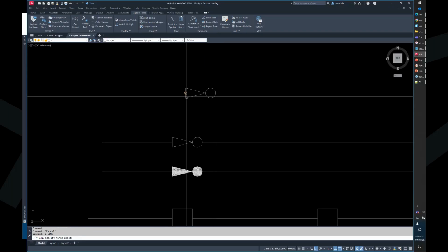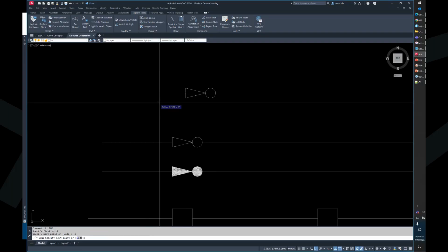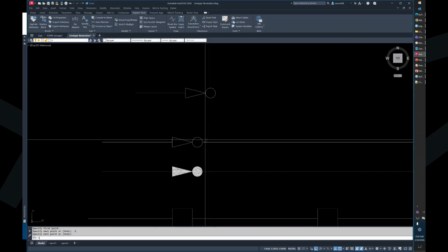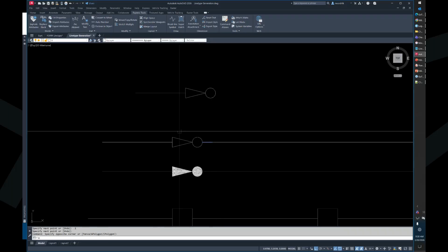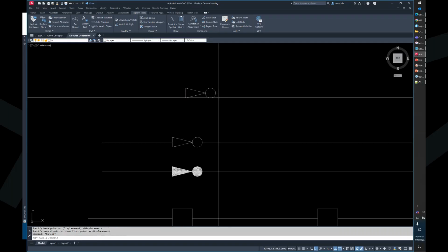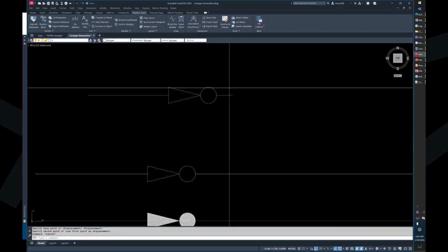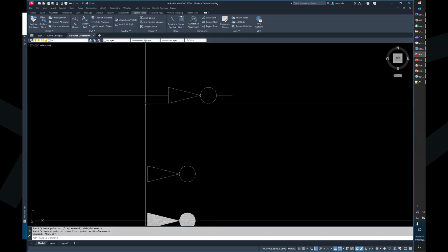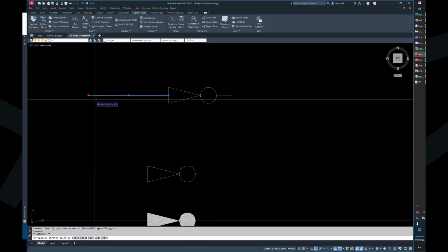And now I can do a line this way, 0.5. And with shapes, there's a little nuance. Generally, if you're creating a line type, you'll want to have a small segment, like 0.1, at the end. The reason is that when the shape gets to an endpoint, the line type doesn't end right there on the symbol; otherwise, you end up with just a symbol right at the end of the line. So usually I'll do that and bring this back in, let's say 0.1.